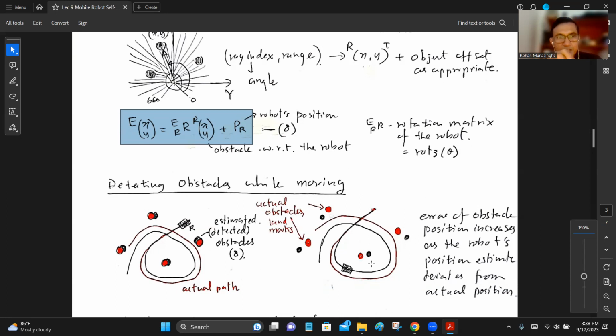So the position change or heading change that will make that happen is the localization process here, right? We will correct the errors in the wheel encoder based localization using the errors between the actual positions and the estimated positions of the obstacles. This is what is called feature-based localization, because the features are actually these obstacles, landmarks. We use the landmark information and their estimated positions and try to change the estimated position of the robot so that these landmarks' estimated positions fall right on top of the reference, actual positions. When that happens, you have the best estimate of the position of the robot. Position means the position and the heading both together.